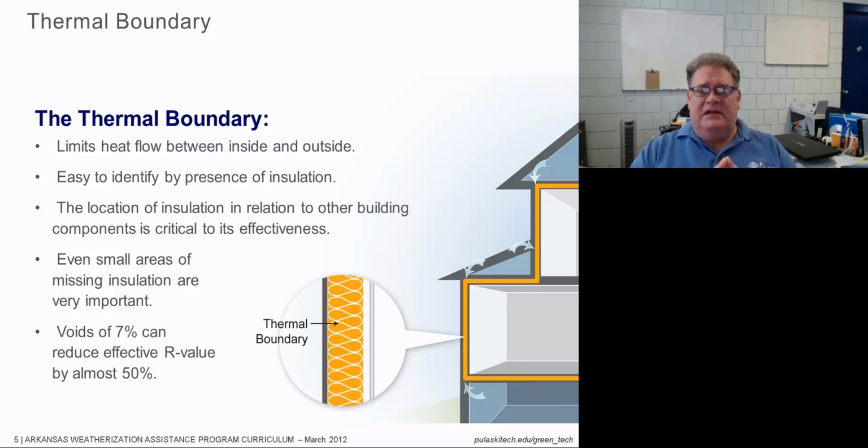The design was to have an attic system that would work to an R40 value. However, because we removed 7% of it, 7% of the floor space has no insulation on it. Now the whole attic system is going to perform as though there's only R20 in that attic.